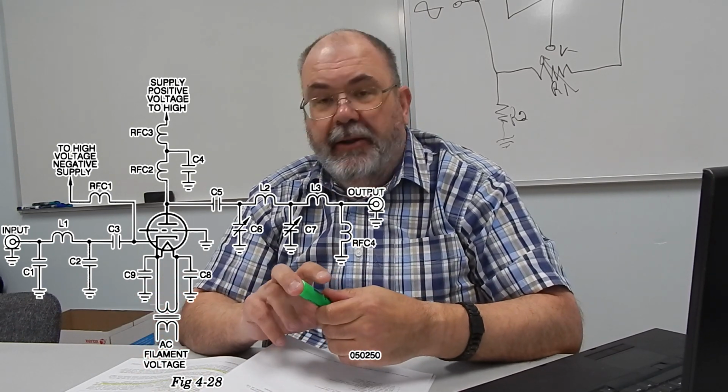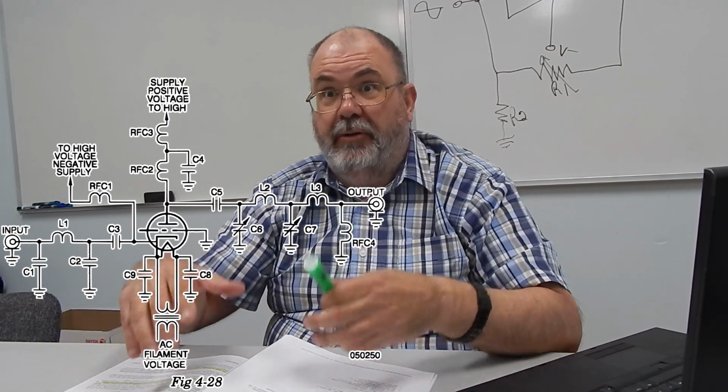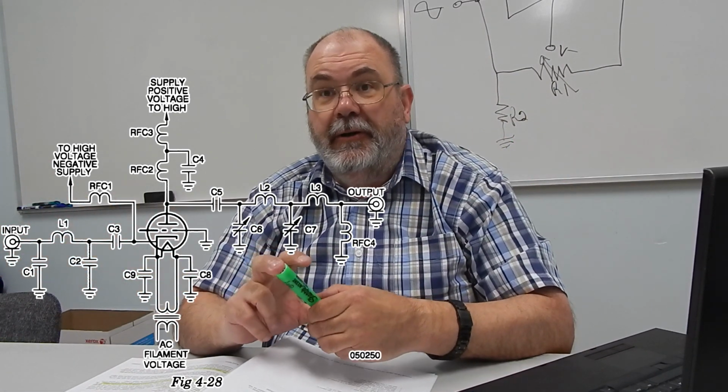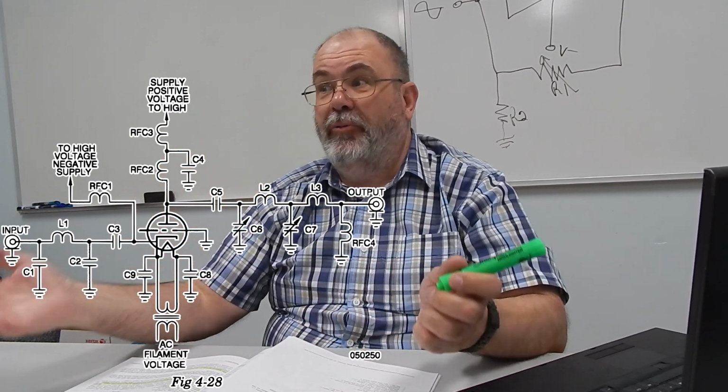In a well-designed, well-built amplifier, a lot of times you get lucky and you don't have to do it. But you will see, even in commercial amplifiers that you buy, grounded grid amps or other large solid-state power amps now, they will build the thing on the assembly line, put it all together, and when they go to test it, the guy will sit there with a soldering iron and capacitors and solder them in by hand to fix all the neutralization problems. Because there's just such slight differences in components and lead length and everything else that no two are the same.